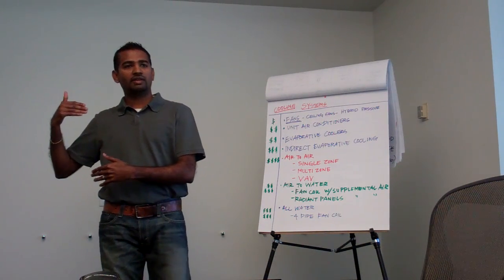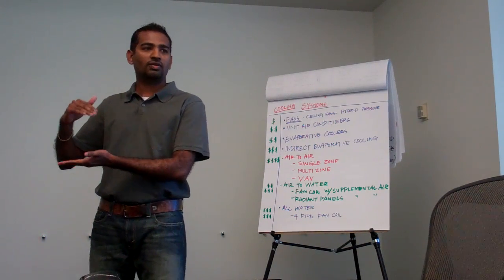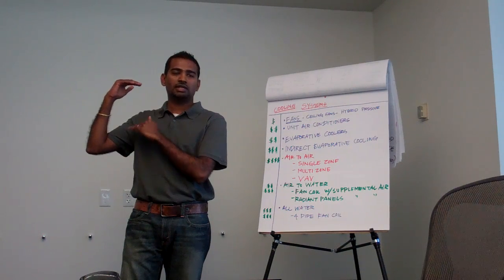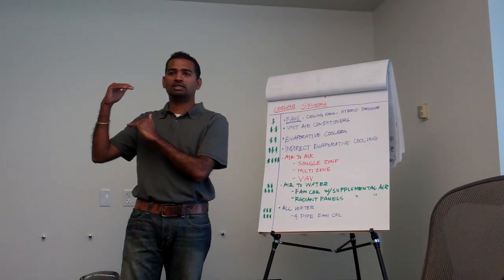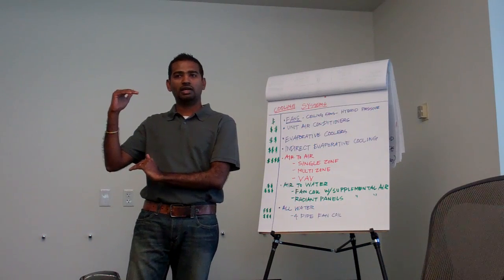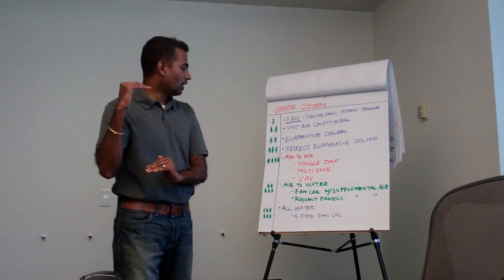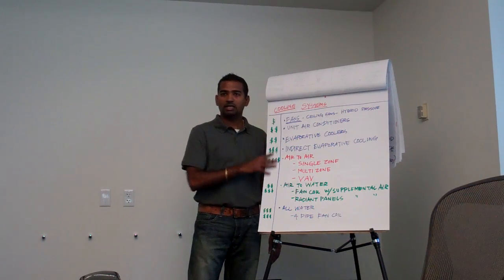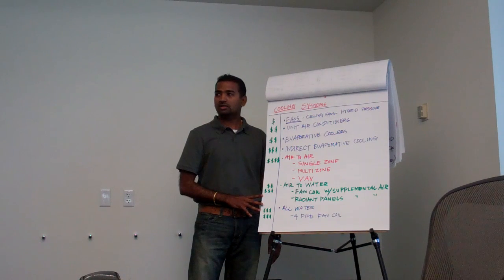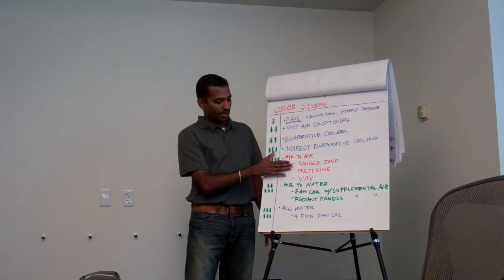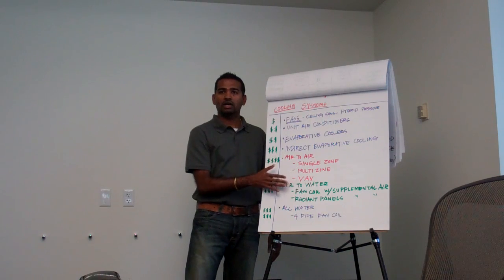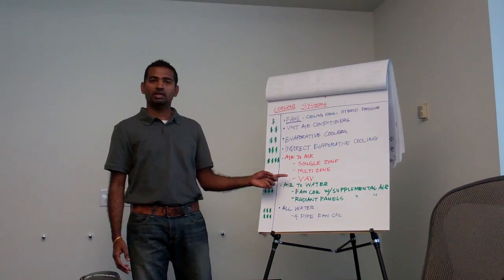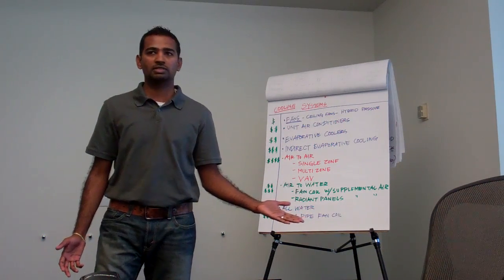the 85, 15% difference, and of the 85, how much can I actually do in my project? Let's say it's only 45% passive technologies. So then my HVAC is 55%. So off this 55%, we should have an idea of where the budget is, right? Typically, budget drives our selection. We should have an idea, because that will determine how we design our buildings. If we go with a multi-zone or VAV, we have to make sure we have plenty of ceiling space.